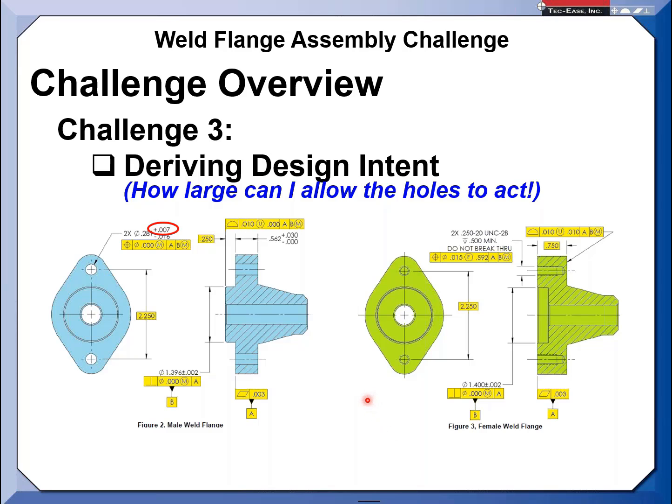There's a lot of tools in the GD&T toolbox, or I should say the 14.5 dimensioning and tolerancing, that you can prove out mathematically to control these boundaries of the collective effect. And with all these features on this part, there's going to be two boundaries. There could be a size and then a collective effect of location with the size. And that's pretty much all I was trying to get across in all these exercises.